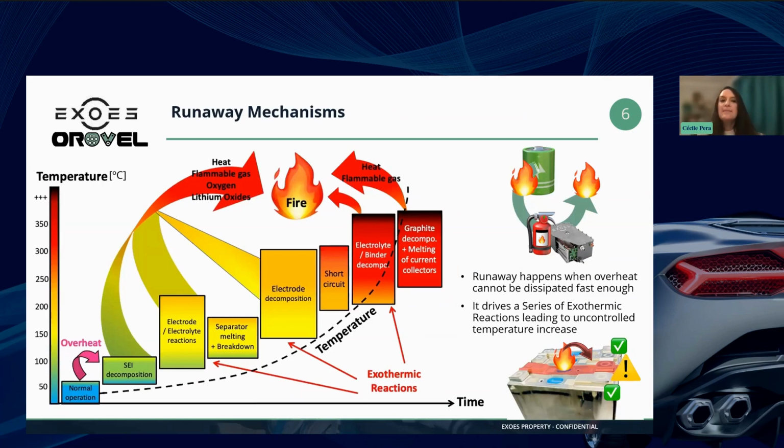So when you look at what happened in terms of mechanism, I want to draw attention to several different things. You have battery fire. You have runaway, which is defined as an increase of temperature, and you have thermal propagation. Runaway can be local or generalized, but thermal propagation defines the fact that maybe you have a cell that gets a problem and goes into runaway, and maybe you are not able to stop this cell from going into runaway.